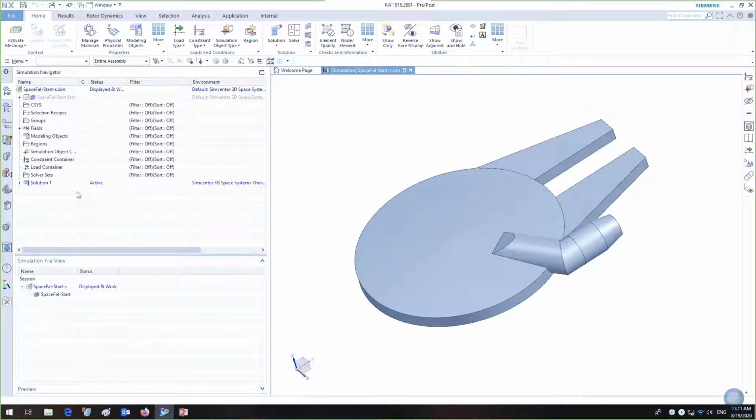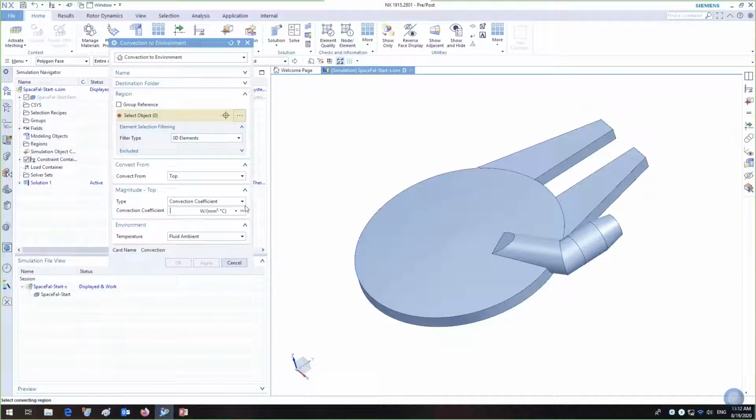And today we're going to be working with this oddly shaped spacecraft. I was tired of using the good old cube example model, so I had a little bit more fun. What we're going to be simulating here is, let's say this oddly shaped spacecraft has to fly through atmosphere. So I have one of my colleagues that ran CFD analysis on this. So I have a field of heat transfer coefficients that vary with Cartesian coordinates that I want to apply on the surface of the spacecraft.